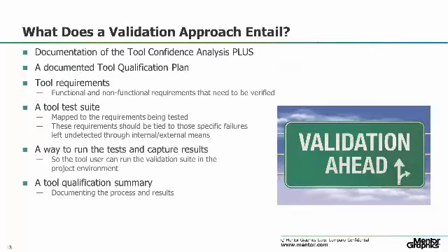If your design does need TCL2 or TCL3 qualification, then you need to come up with a qualification plan which identifies tool requirements, a tool test suite, how you run the tests, and then documentation of the results of running that process. And this is an area where we will be happy to discuss with our customers how we can assist in setting up things like the tool test suite. So if there are tests from our QA environment that we might be able to make available, things like that.